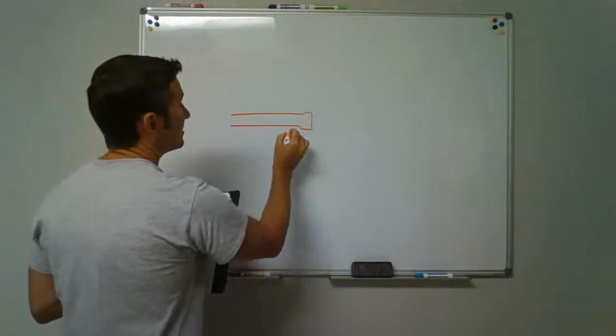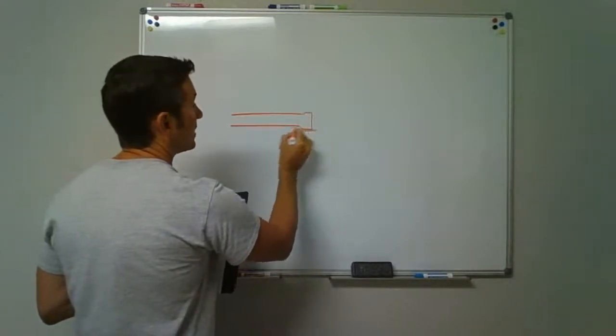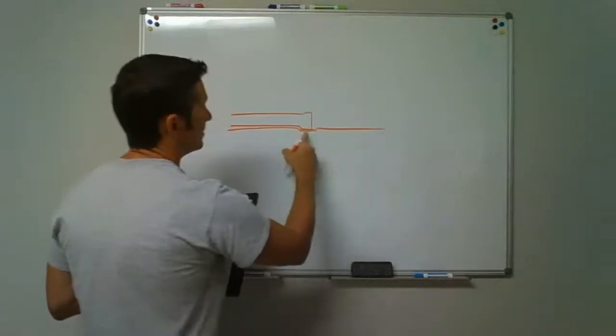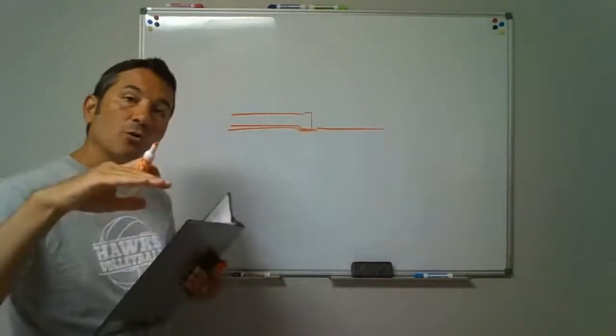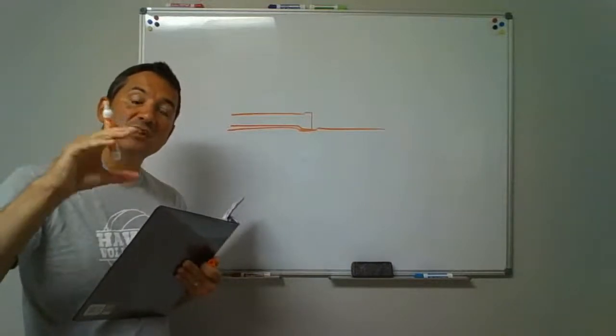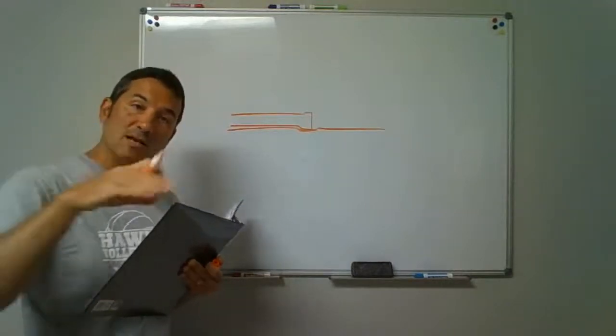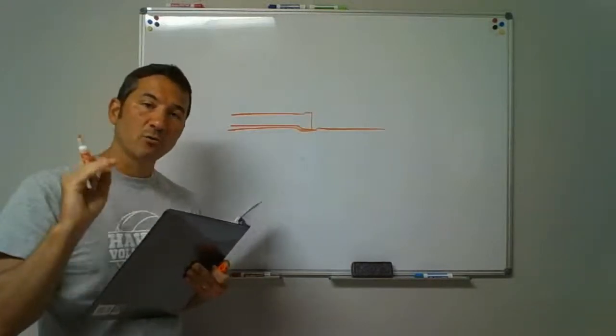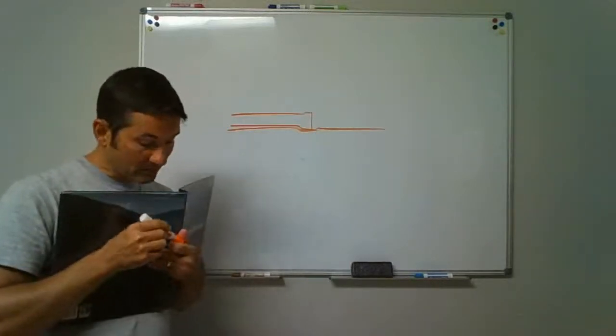Okay. It says to dig out a little notch in your ditch to account for those bells, so all the weight of the pipe's not sitting up on that little bell. Okay. It makes little notches for those. It says the bottom of the bed of your ditch ought to conform right to the bottom of the piping.